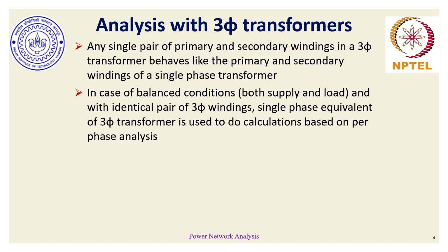But now, apart from those single-phase to three-phase conversions, in three-phase transformers we have these additional phase shifts of plus or minus 30 degrees. So the overall simple KCL, KVL application won't be so straightforward. And that is essentially what is enumerated in this slide.